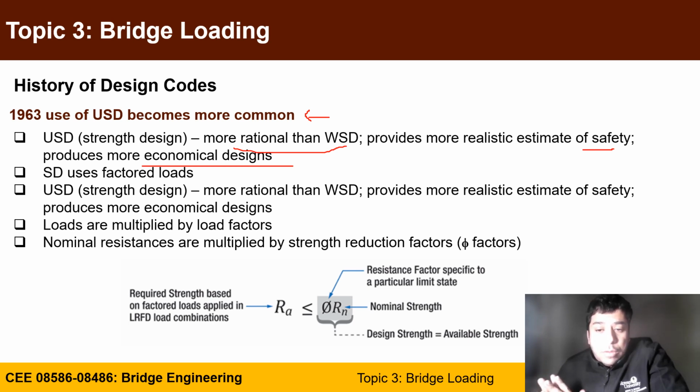We always go in estimating the capacity of different systems or elements such as concrete girders and steel girders. We know pretty much the cross sections. We know pretty much what type of materials. We have control on testing materials. So we don't need to reduce it by that much. We reduce it by a little bit, which is a reduction factor in strength.